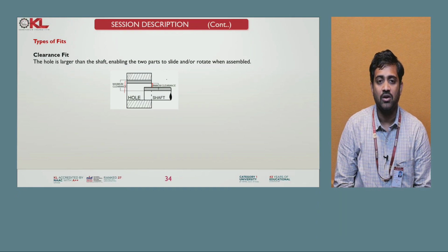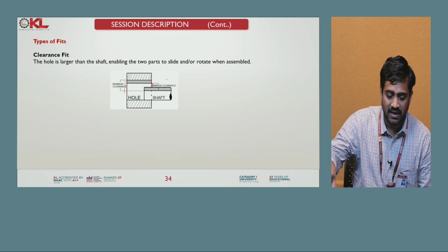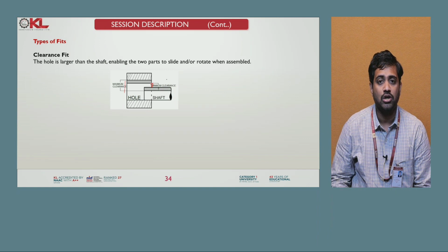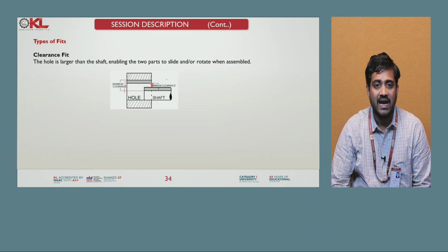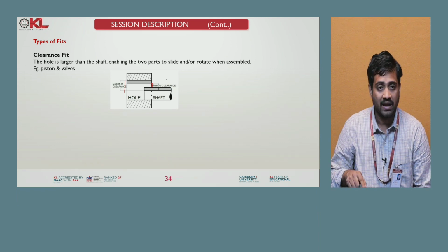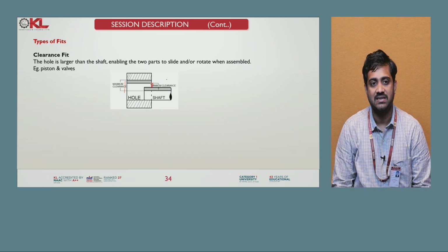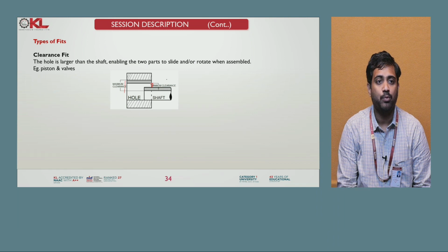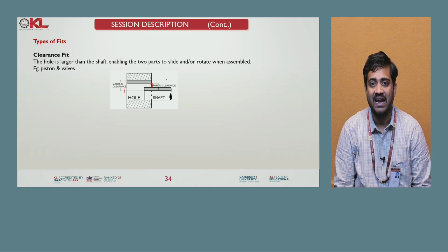See, when you use this clearance fit, you see some clearance, minimum clearance is there, with which the shaft can slide or rotate in the hole after assembly. Examples: pistons and valves. The piston is designed to reciprocate inside a cylinder head.